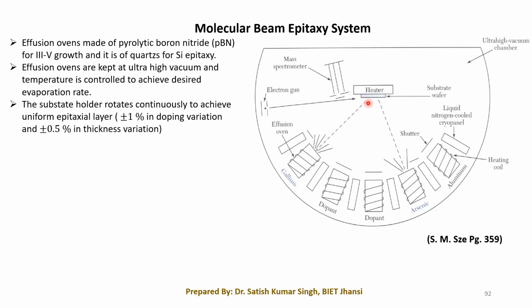Now, one more thing is the RHEED pattern, in which we monitor the quality of the grown layer. That is basically used for research purposes. But in commercial products, when we are doing MBE commercially for epitaxial layer growth, then generally we are more interested in growing a uniform layer, a uniform epitaxial layer onto the substrate.